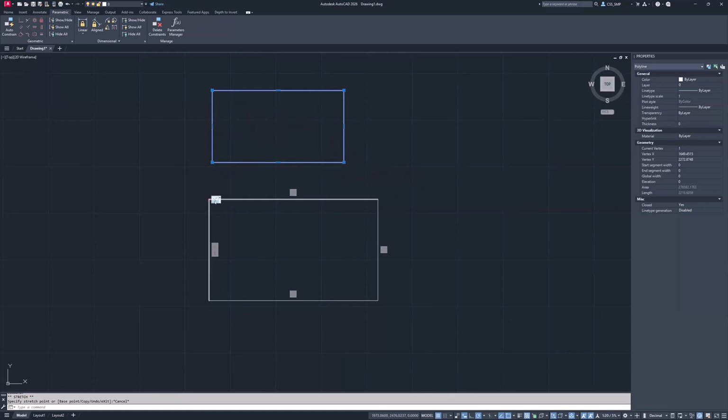If I was to remove the perpendicular here, if I right click on here, I have a delete option. If I hover over here and click the X here, that will only hide the constraint. It will not delete it, it will stay. So if I right click here and go delete, we've got parallel for these two lines, these two vertical lines, and we've got parallel and parallel here.